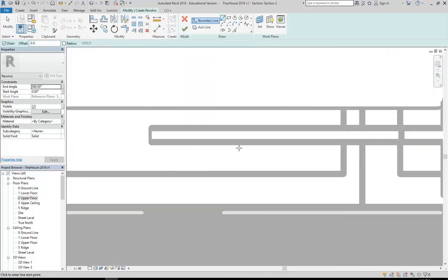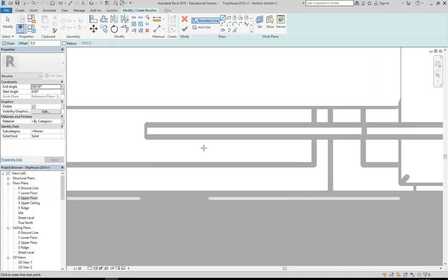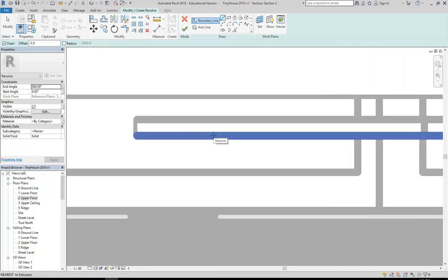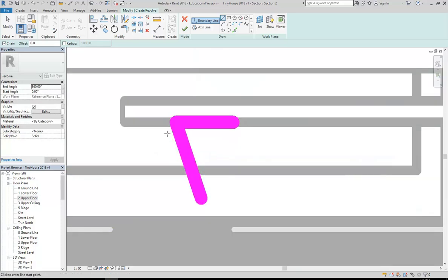And then I'm going to draw the profile. And this is again from a real shelf that I designed and had built. So my profile, I'll start on the bottom of my shelf and then come across and then down at an angle. So that's how it looks from the outside. It's sloping, a sloping leg. I'm just going to draw this side straight down, and then it had a rounded bottom. So I'm going to use the arc tool again and just draw an arc from the end of this line across to the end of the other one, and then take it down so it's got a nice curve there.